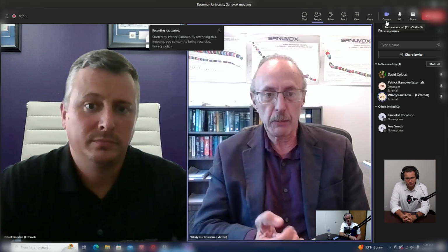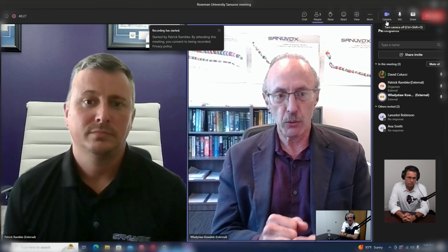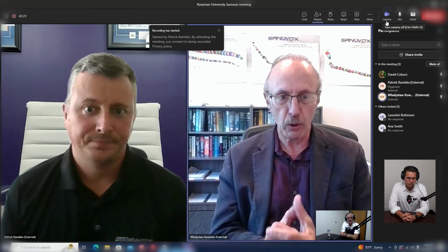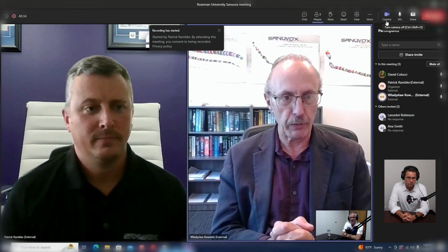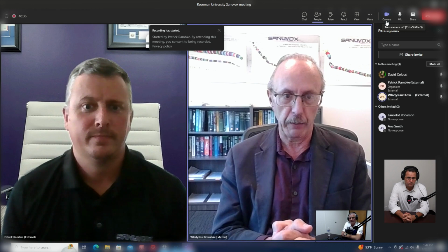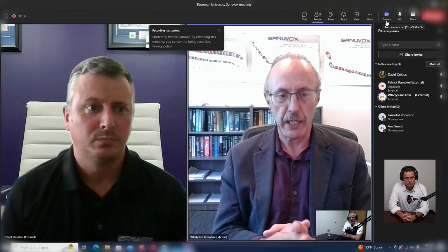For in-duct systems, of course, ASHRAE dictates how much air is delivered to the room, whether it's for personnel comfort and breathing or for heating and cooling. And therefore, whatever is required to be the airflow rates, we simply size the UV systems for the existing airflow rates or the predicted airflow rate. So it's pretty cut and dry in most cases.